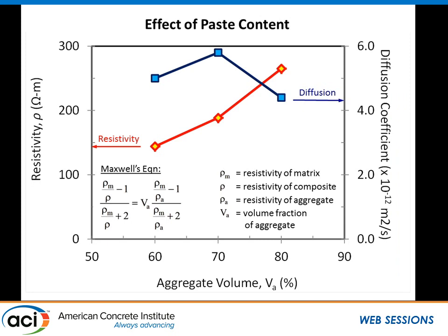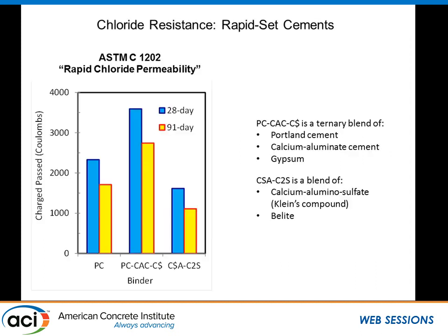we'll notice with electrical resistivity measurements is that usually the matrix has a much lower resistance than the aggregate. What this means is if you change the amount of paste in your sample, or you change the amount of aggregate, you're going to see a fairly significant difference in the change in resistivity. The more paste you've got, the lower your electrical resistance is going to be. Or I should say the more aggregate you've got, the higher electrical resistance is going to be. And this won't have the same impact on chloride diffusion. Chloride diffusion will be dependent mainly on the water binder ratio of that paste rather than the quantity of the paste. So it's just another little thing I thought I'd throw in there.